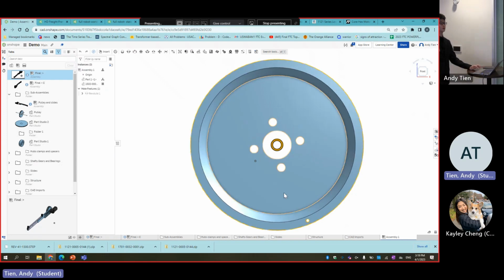So what this is for is, first of all, you can just flex on your friends by having your CAD robot move in the CAD software. But more importantly, this is going to allow you to move your part like on the actual robot, and you can turn whole assemblies left and right compared to other assemblies. And you can check to see if there's interference between parts. This would be really useful before you 3D print something, to know that, is this part going to function correctly in the range of motion that I've defined it.